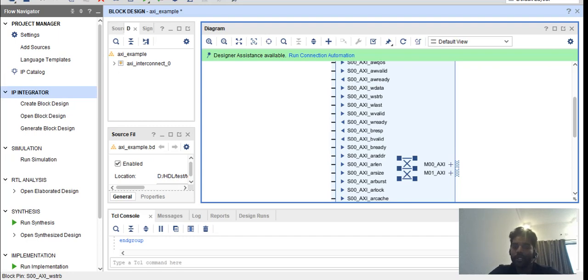So this will be taken care by the master, because the master is already having the settings like the configurations, like how many bursts to be sent for each address, right? So once the address is initialized, the write data channel will be ready for you to send the data. So once you initiate your valid, this valid has to be valid till the burst type is end. So based on the burst type, you can keep this valid active.